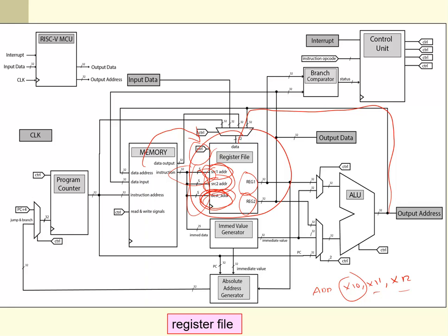associated with a jump instruction. If you remember, the jump instruction saves the address of the PC in a register, and you can see that connection right here. And lastly, it can be the input data. Input data goes, by design, from the outside world into a register file. So those are the 4 pieces of data we can put into this thing. It's defaulted to 32 bits, which supports everything, although your I/O may not be 32 bits.